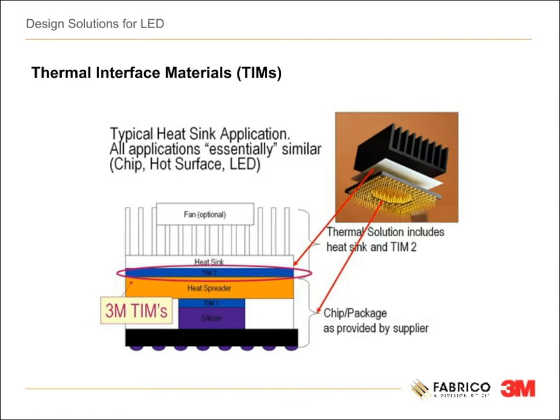So, if I have a heat sink, why do I need a TIM, or thermal interface material? TIMs are an integral part of any assembly that includes a heat sink or heat spreader. The TIM sits between the LED and the heat sink and provides high thermal conductivity to efficiently transfer heat to the heat sink. Without a TIM, gaps and spaces between the LED substrate and the heat sink lead to inefficient heat transfer and degradation of LED performance. When an LED overheats, it can change color, lose illumination, and eventually fail completely.